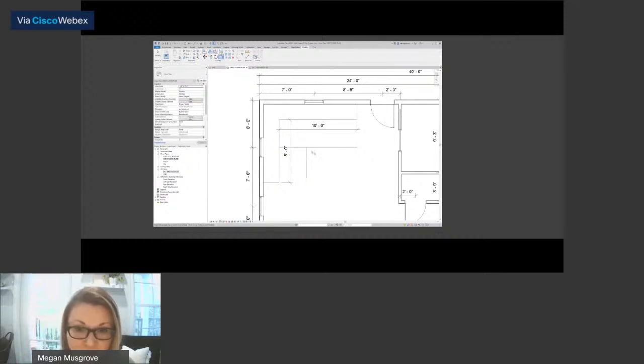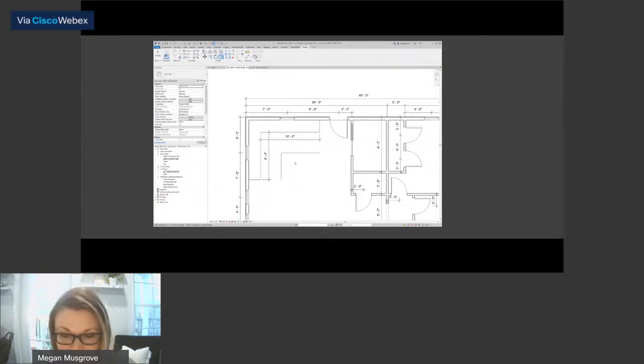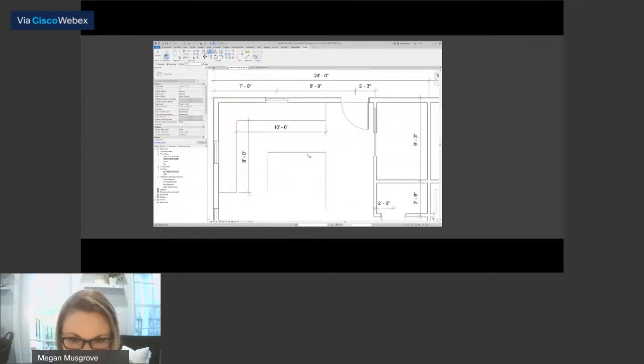We're going to do trim to trim those up. And then let's do DL to just make a line over here. I'm going to just drag that over there. We're going to offset again, OF. And let's actually leave that at 3.5 feet. So what we're going to do is complete this.